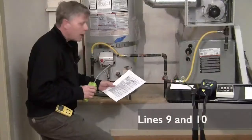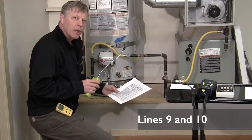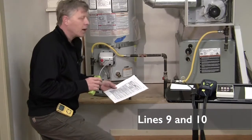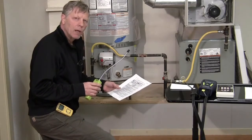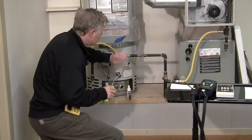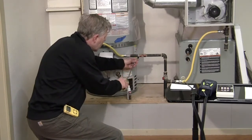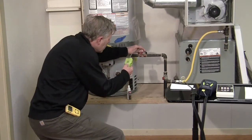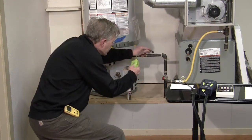All right. Now the LEL is 0. We're going to use our combustible gas leak detector to check this gas line for leaks. As I said earlier, we're only going to check a few joints to show you how to use the device, but you would be responsible for testing all the gas lines in the house. So I'll check a couple joints here. I'll run the head of the detector around each joint, taking about 1 second for an inch of travel.